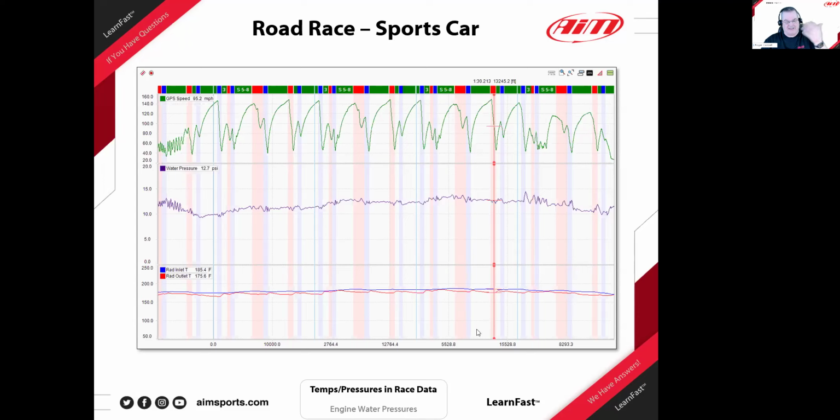Most of us would think, at least I certainly do often think this way, that there will be a much larger delta difference in the temperature of the water coming into the radiator. Now that's the radiator's job, but not always is it that way. And you should know that if you're depending on that. And maybe in this particular case, the driver had it kind of covered for aero reasons. And this is a pretty fast car, approaching 160 miles an hour at VIR. Maybe it only needed so much air to keep the water temperature down, and he's happy with that. But you should know that.